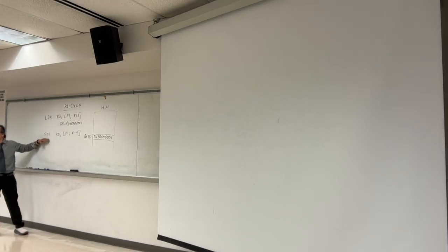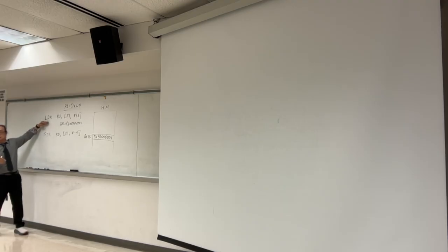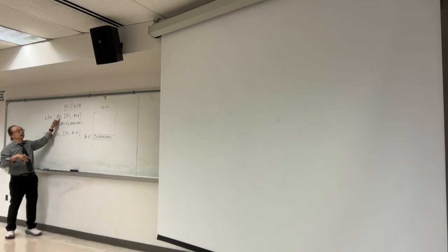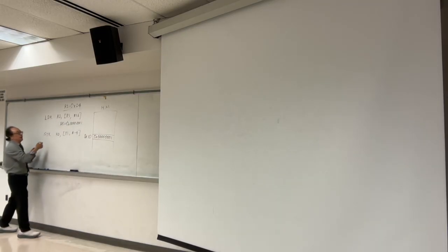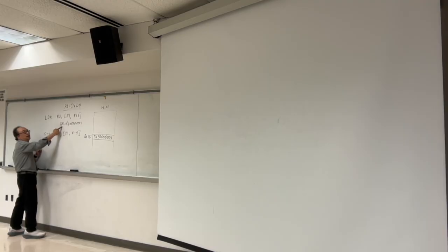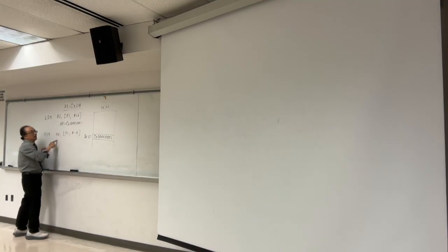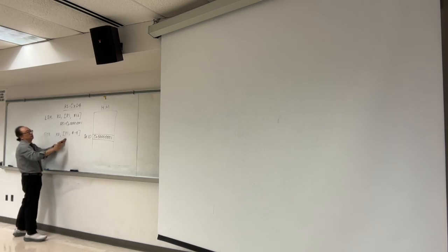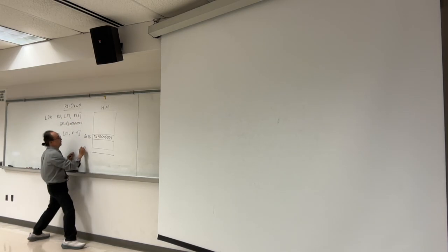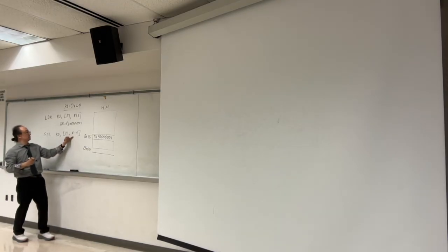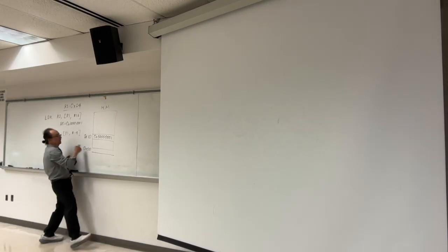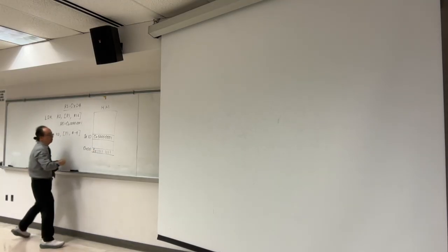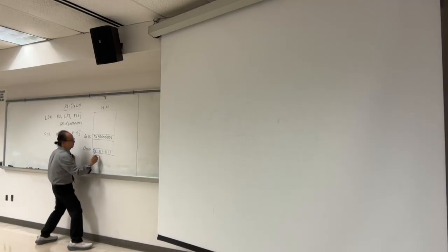So here's the two things. LDR, STR, we need to access the memory. LDR, we're going into memory, take the contents of memory, put it into register. STR, initially we said R0 was 0x0001. We're going to store this into main memory, where R1 is 4 minus 4, the very bottom, which is 0. That's the location we want to store this into. Initially we said this. Now we're going to replace this.